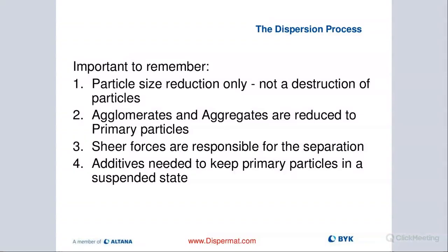So just a few points here. Remember that we are really trying just to reduce particle size by breaking up these van der Waals forces and not really destroying our particles. There are some opinions out there, or thoughts, that if you are milling, the beads will actually crush your pigment particles, but that's actually not really what we're trying to do here. We're just really trying to increase the shear by using media, and that shear will allow us to basically separate these pigment particles. Destroying them or crushing them between two beads does happen, but it's actually pretty improbable